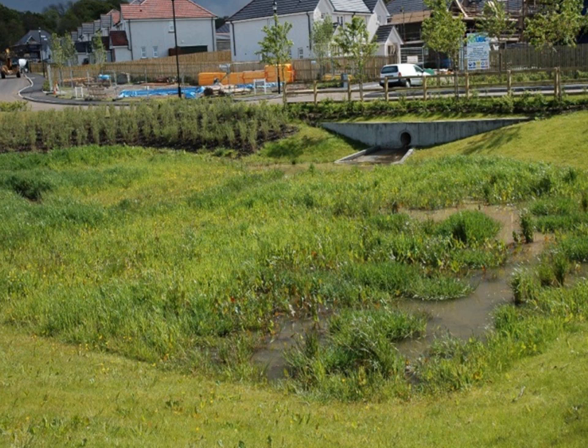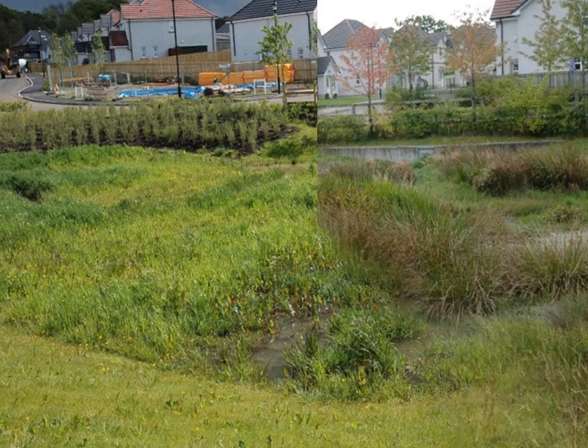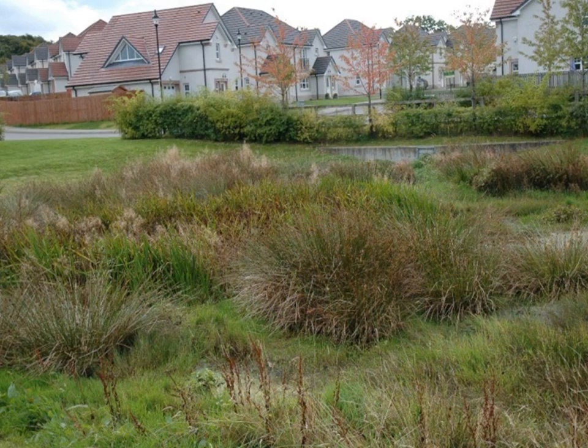This image shows a larger picture of the retention basin from the previous slide when it was first constructed. The construction of the housing estate in the background, as you can see, is still taking place. Five years later, the vegetation around the wet pond area has been allowed to grow, creating a miniature wetland pond area. An interesting point is that the only barrier between the SuDS device and the public road is a hedge to protect the inlet culvert. The rest of the site is accessible from the public road.